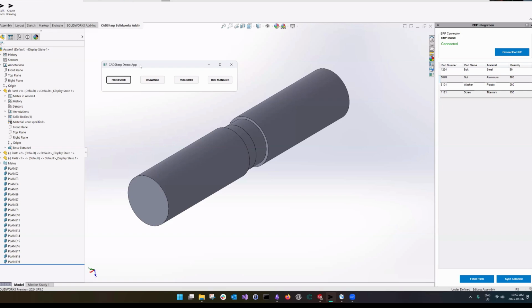So if you need to process many SolidWorks files, we would prefer to handle that from a Windows process that launches SolidWorks, opens files, and closes SolidWorks. That's so we can handle cases where SolidWorks crashes. Realistically, if you're processing thousands of files, you will encounter a hangup at some point. If we do that inside of SolidWorks via an add-in, we can't handle the use case where an error comes up inside of SolidWorks, a file fails to open, et cetera. So these apps control SolidWorks externally, and if SolidWorks crashes, they simply log it and then try again or move on to the next file.